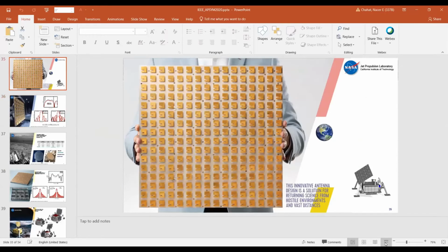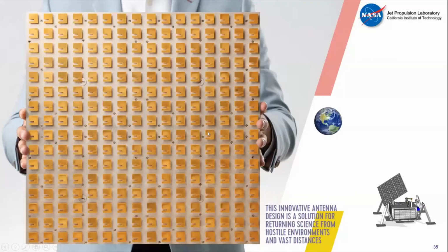Excellent question. The element here is actually excited on these bottom points, and at the center we have a post that allows us to be directly in contact with the ground plane. So everything is in metal and holds against each other thanks to this post in the center. It's located in an area where the current is very close to zero, so it does not interfere with the RF of the patch elements. But the reason why we have this slot is to get the circular polarization at 2 frequencies. That's an important thing.